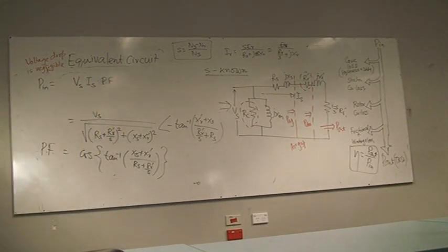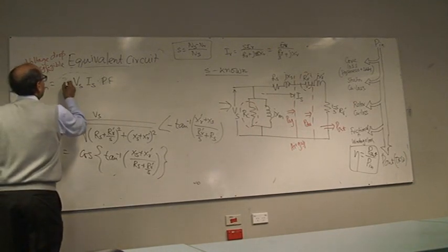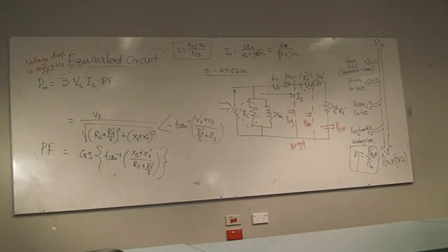But this is not a single phase motor, this is a three phase motor. So you have to include all the three phases and multiply by 3. We are analyzing only one phase, but it's a three phase motor, so you have to multiply by 3.